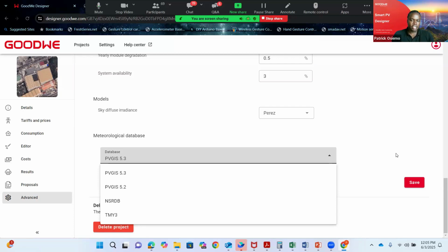Otherwise, you need the actual architectural drawing so that you get to know the exact dimensions of the floor plan and the roof. Also, you have to do a physical visit in case the images are outdated. Probably there are other obstacles that were not there four or five months ago. A site visit should eliminate such unforeseen instances. So it does not fully replace your as-built drawing; you have to confirm with architectural drawings as well as site visits.